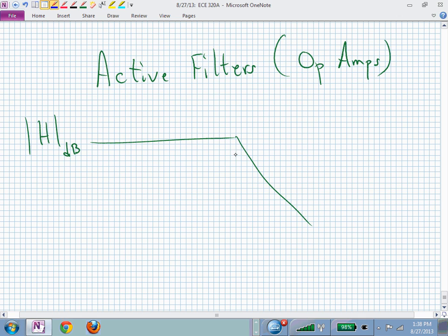In this picture, that's maybe our cutoff frequency, or where we start to change from passing frequencies. That's our pass band, and our cutoff frequencies, or the stop band frequencies, are those frequencies that we're trying to get rid of. And we'll try to build these up, and maybe we want to really make that transition from the pass band into the stop band really, really sharp.